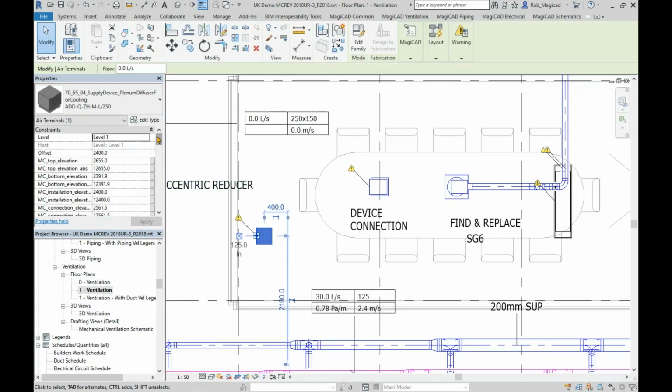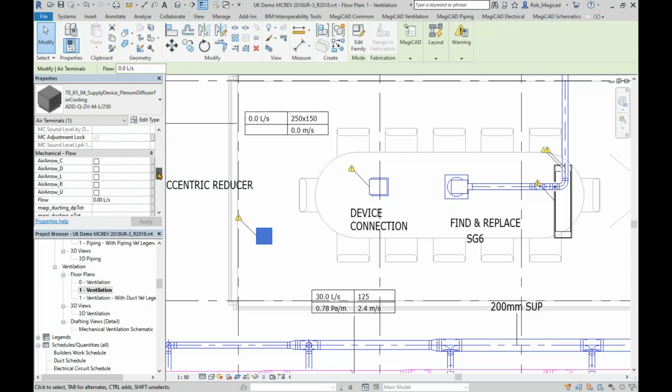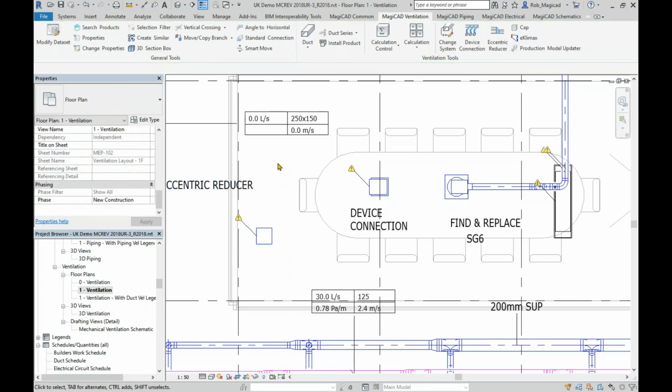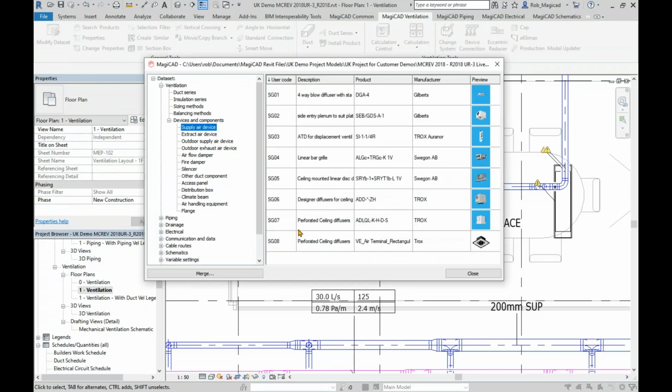If I click on there and go down to identity data in here, you can see the parameter exists with the default value of today. So the idea being that you can go into this data set and create as many parameters, as many products as you want with those parameters, and that can be your default, so any project in the future can also use them, so you can save yourself a lot of time recreating that.